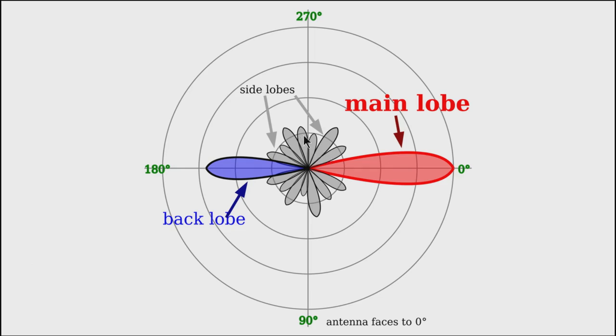some of these lobes are overlapping with each other very close in, and there could be other objects in here, other pieces of metal. In the case of higher frequencies, VHF, UHF, somebody standing there could make a difference. But when you're near in, that pattern's going to change as you move out. These lobes aren't going to be overlapping with each other.